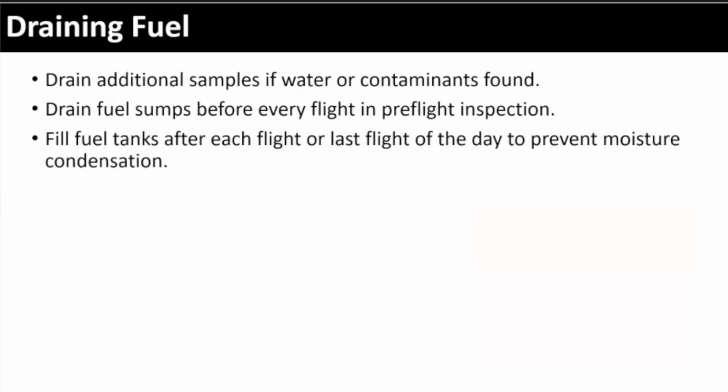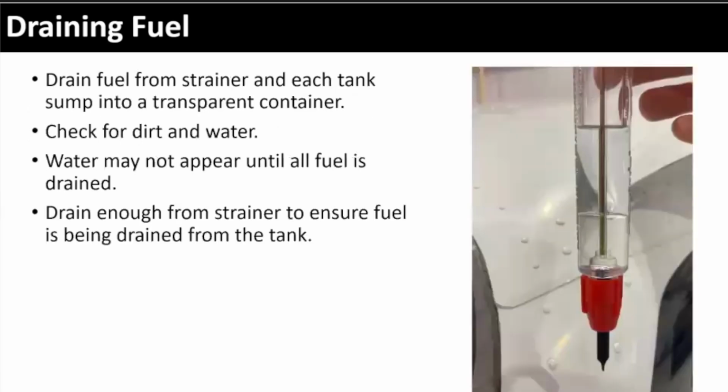Okay. Yes, sir. Is that image with water in the fuel? Yes. Good point. So here you can almost see that it's blue. And you'll notice it immediately. If you've got water in your tanks and you're draining from the sump, the water is going to sink right to the bottom of that fuel tester. Right. It's going to be quite obvious.